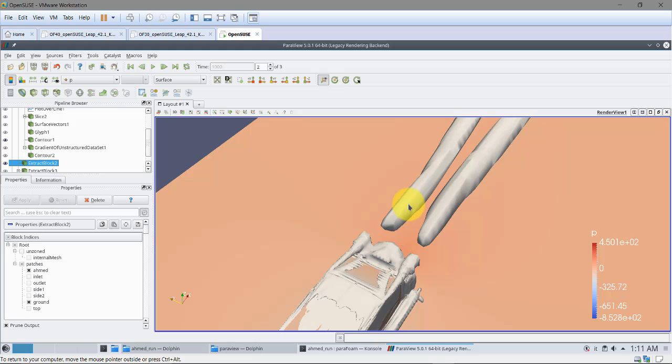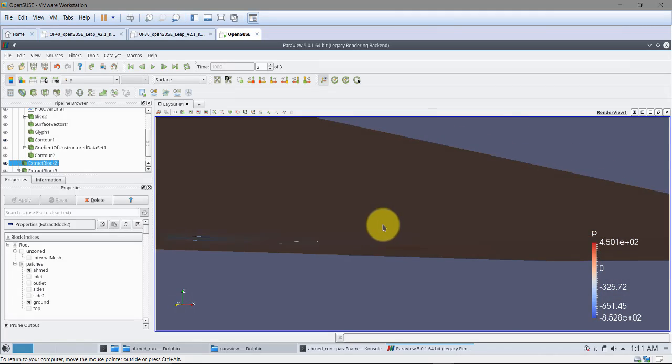But also, for instance, sampling: sometimes it's easier to do sampling here, and you don't get the same problems that you have when doing the sampling in OpenFOAM. Sometimes you have problems running in parallel at boundaries as well. You can have strange stuff. So doing the sampling here is way better. Just get your script and then just repeat it.